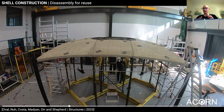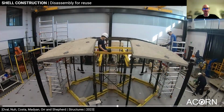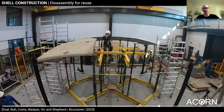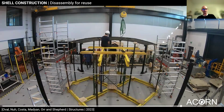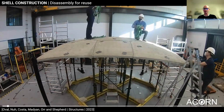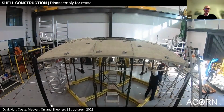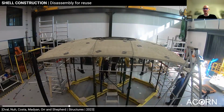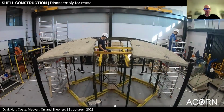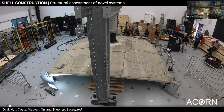And thanks to the detailing that we had, so dry joints to be able to disassemble them, we use them as such. And that's actually what we first did, a fabrication, let's say an assembly test at ground level to be able to make some corrections that we had to do because we were within, let's say, half an inch in terms of precision, so we had to make corrections. Then we did the assembly test on the columns to showcase what it would look like as a prototype.